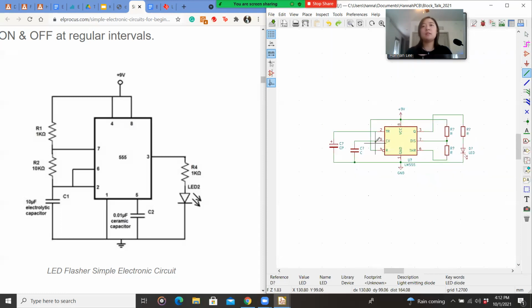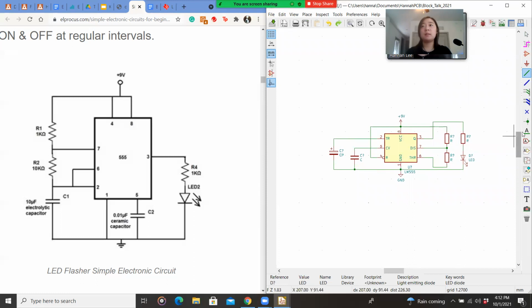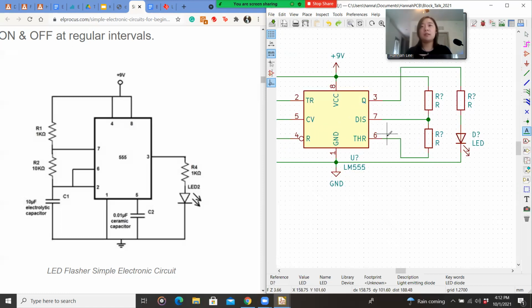Well, what we can do is that KiCAD provides something called labels. And if we click here, we can actually place something called a label, which basically tells KiCAD, hey, we didn't actually connect the trace between here, but we wanted to, and we intended to. So there's actually supposed to be a trace between these two things. Go ahead and connect them or treat them like there is a trace or a wire between the two things. So how do we go about doing that?